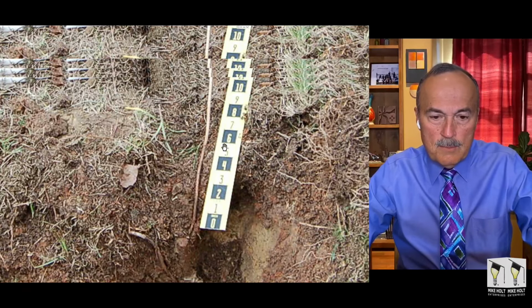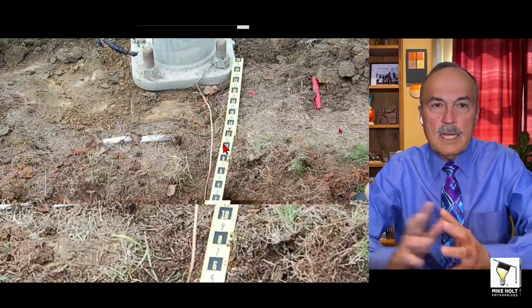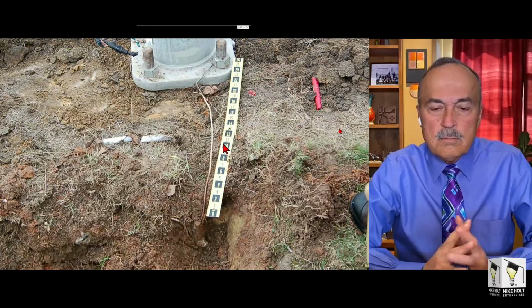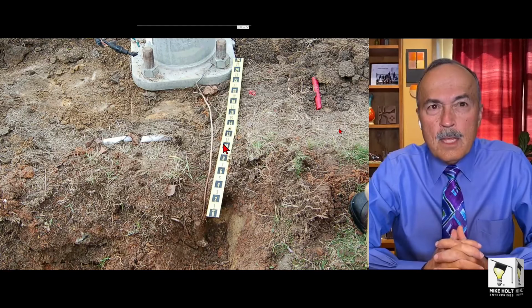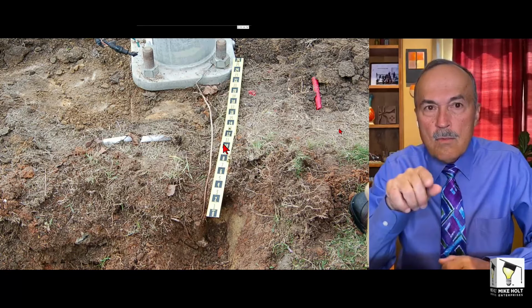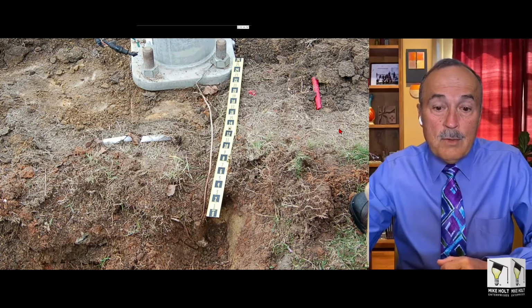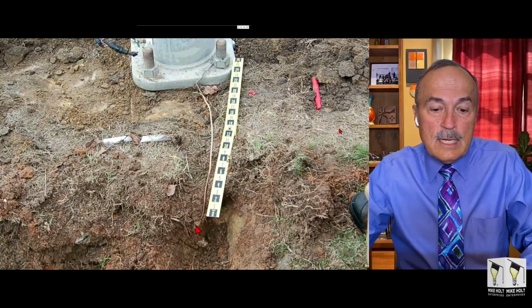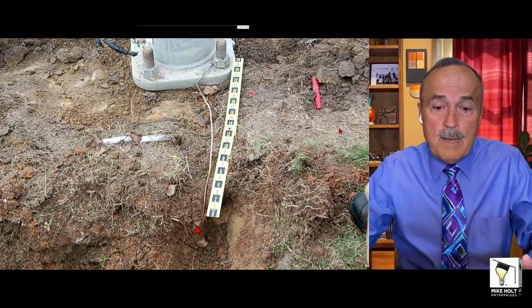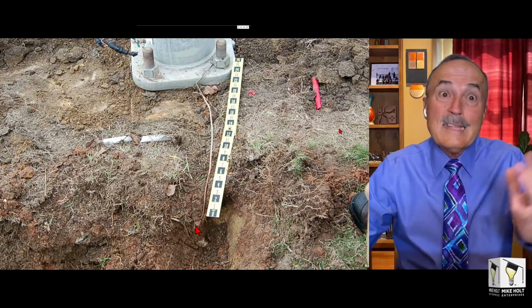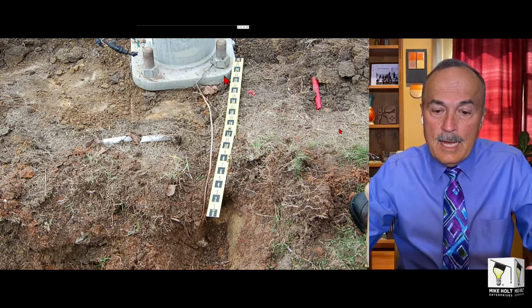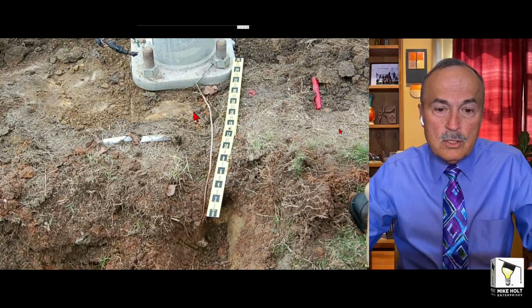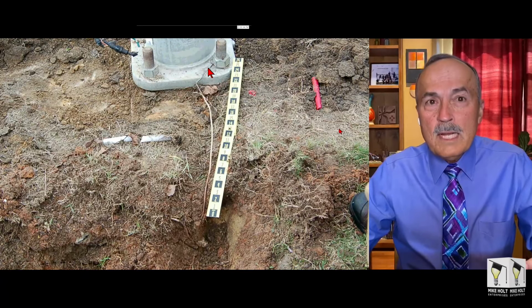And you know what's interesting about this case? I was involved in this case, but I gave it to a buddy of mine to manage. That ground rod, by the way, is called an auxiliary electrode. Not required by the code, it doesn't serve a purpose at all, but people do it because they think it's a good idea. And they had no equipment grounding conductor in the circuit. There was a ground fault, and the pole became energized.